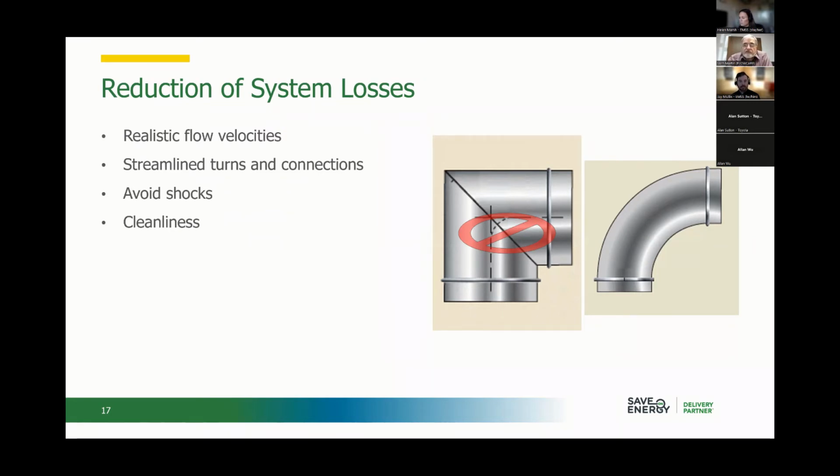This is the whole thing with the system approach, is that once you start doing this sort of thing, every one of these things reduces the required fan capacity you need. Maybe I'll show you this one here too. You can see it's got a smooth entrance here. It's got a rounded surface. So if this is on an entrance of a duct, then rather than the flow coming into a square edged orifice opening, you've got something that helps it get around the corner. And so you end up reducing entry losses with that.